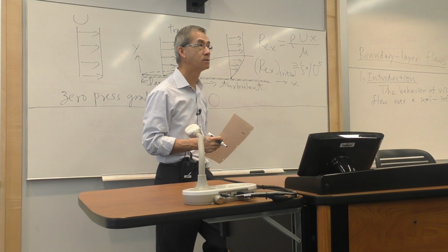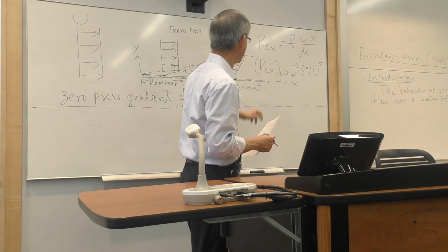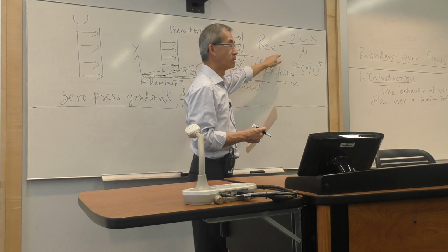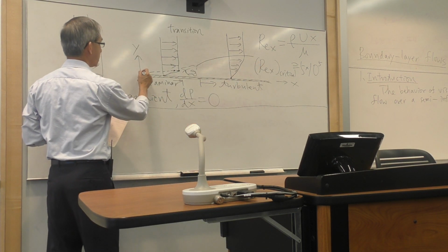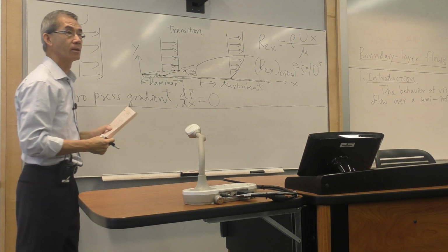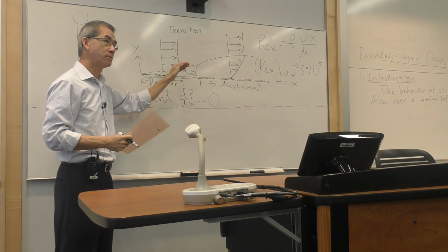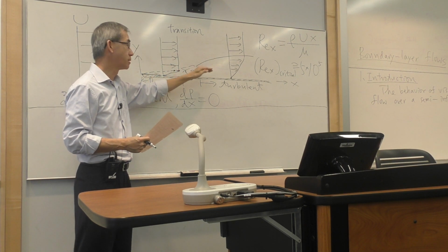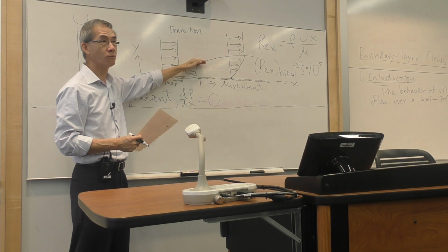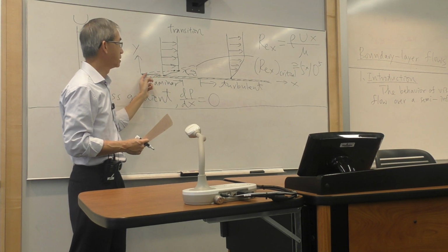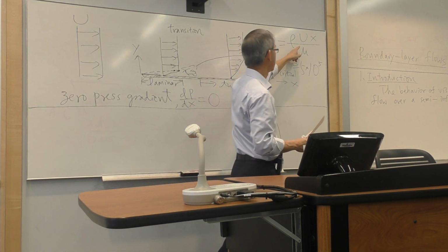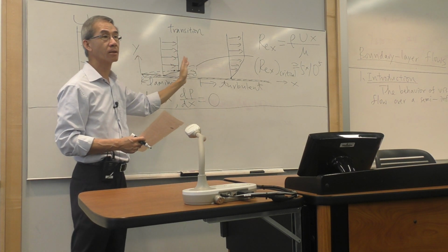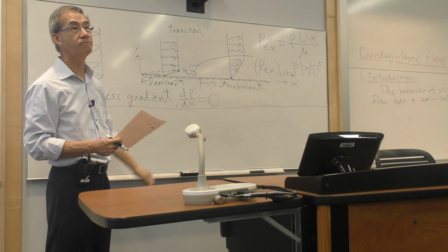Yes? So that Reynolds number is defined, why is it, how does the x distance come into play? The x distance is measured from the leading edge on down, and as I go down the plate, the boundary layer will continue to grow, and allowing this x as the length scale to characterize the Reynolds number allows me to look at the transition between laminar and turbulent flow.